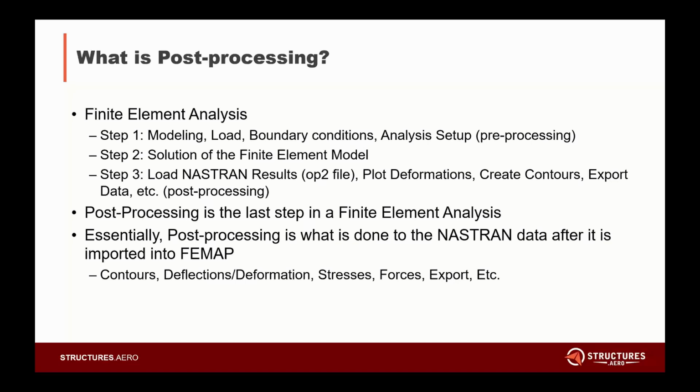You'll hear me reference that later on. So you load the results, and you're plotting the deformations, creating contours, exporting data, plotting deflections. All that is done after the solution of the Nastran model, and that's known as the post-processing. It's essentially what is done to the Nastran data after you've imported it into Femap.